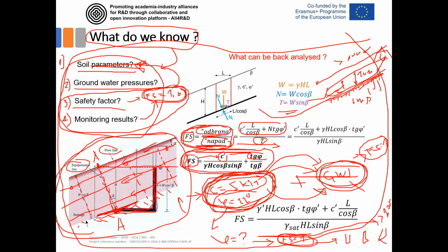Anyway, when we define the same equation including the water pressure at the bottom, as we said for this block-to-block sliding, the increment in pore pressure will reduce the normal stress at this sliding plane. The reduction of normal stress will cause the reduction of this reaction force, and that's the reason why the resistance will be lower in comparison to the condition where there is no water pressure.